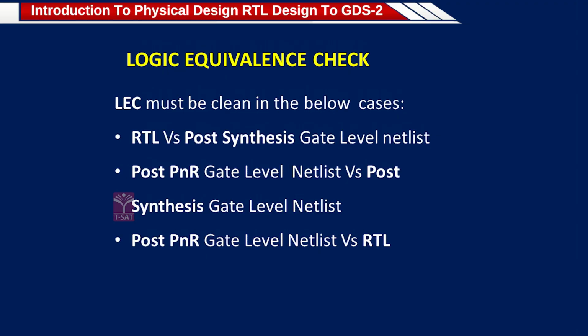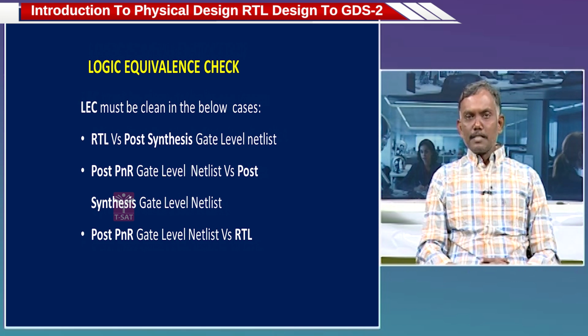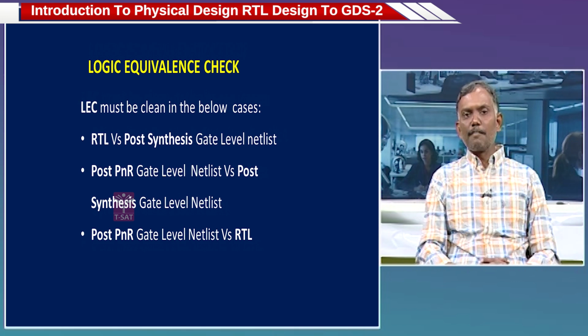Next sign-off check is the logic equivalence check. This logic equivalence check has 3 stages. One is RTL versus post synthesis, meaning after synthesis. We already discussed that we did the logic equivalence check after synthesis, that is RTL versus post synthesis.